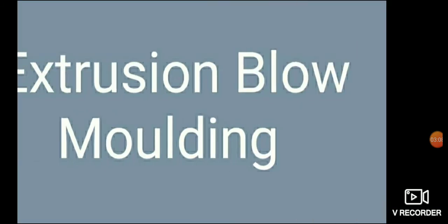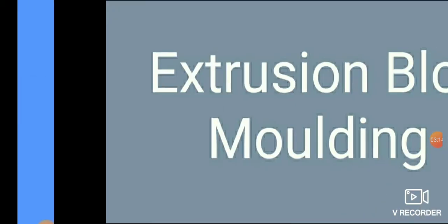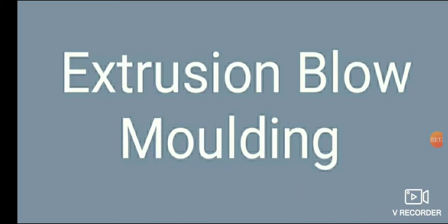The second one is extrusion blow molding. Extrusion blow molding is recognizable by the hollow tube that is extruded from the machine to create the parts. This tube is referred to as a parison. A hollow molten tube is formed, and the mold then closes around the parison and cycles to the blow station. When at the blow station, the parison within the mold is blown using air pressure, while another parison is being extruded from the machine. This allows for a quicker cycle time.